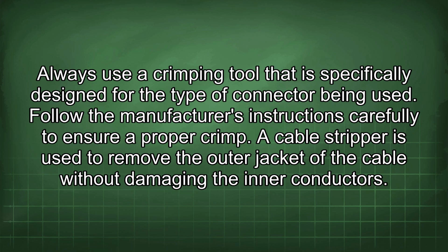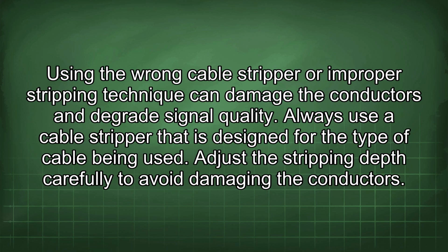A cable stripper is used to remove the outer jacket of the cable without damaging the inner conductors. Using the wrong cable stripper or improper stripping technique can damage the conductors and degrade signal quality. Always use a cable stripper that is designed for the type of cable being used. Adjust the stripping depth carefully to avoid damaging the conductors.